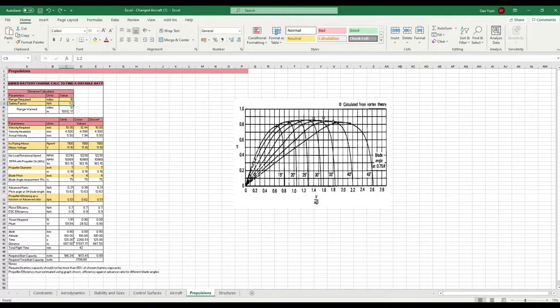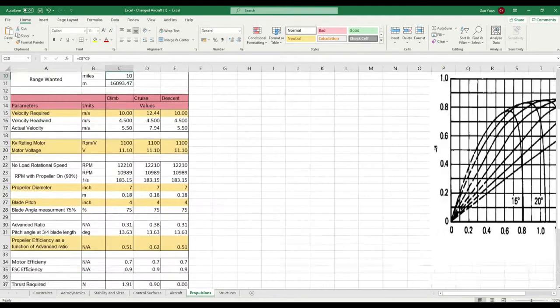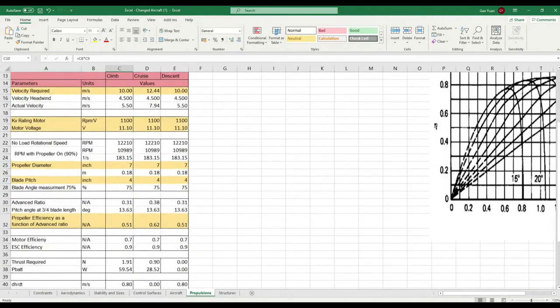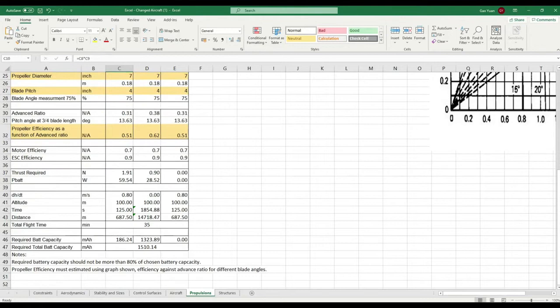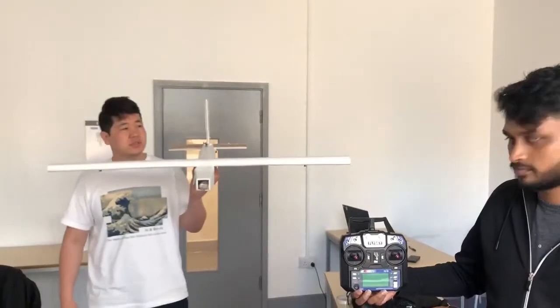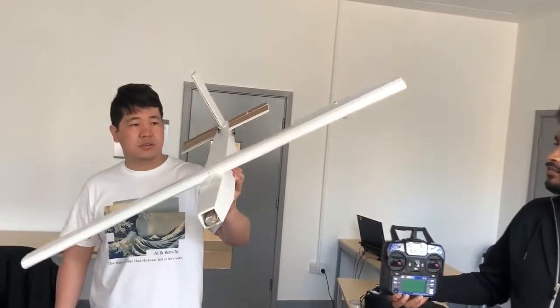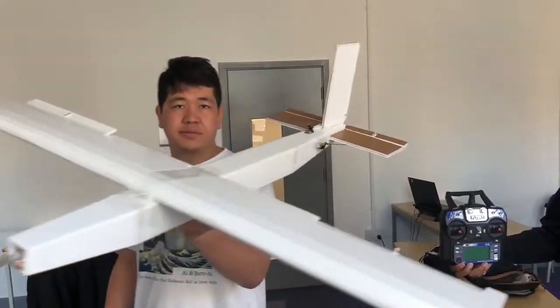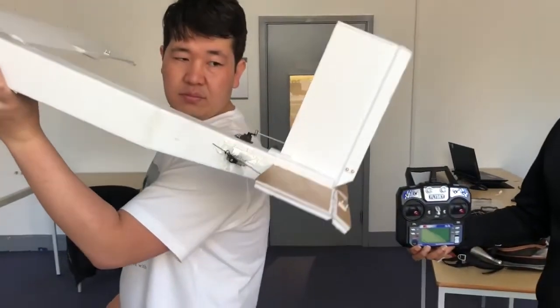At this weight, calculations showed the MS-621 has a range of 12 miles, 2 miles further than required. With a cruise speed of 17.9 miles per hour, the MS-621 is capable of fulfilling the mission in only 35 minutes. With a drone required to reach isolated areas, the need for an autopiloted system capable of ensuring stability when beyond visual line of sight is vital.